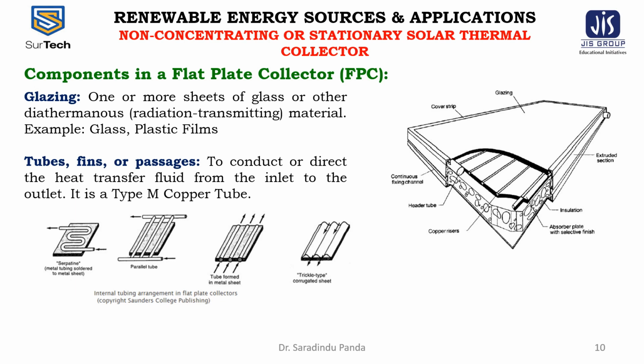Phase change liquids can also be used with the flat plate collectors. Some refrigerants are included in this group of fluids. They do not freeze, which eliminates the troubles explained above for the water, and due to their low boiling point can change from the liquid to gas as the temperature increases. Those fluids can be practical in settings where a quick response to rapid temperature fluctuations is needed.